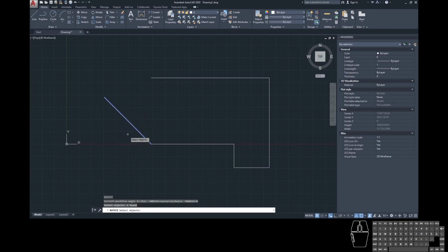We're going to select that object. We're going to select the midpoint this time. So now you can see that it's rotating around that center point. You can also use the snap to decide the angle rather than typing in a specific angle, though typing in an angle is obviously going to be your more precise option here in most instances.